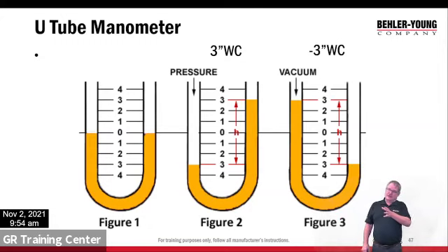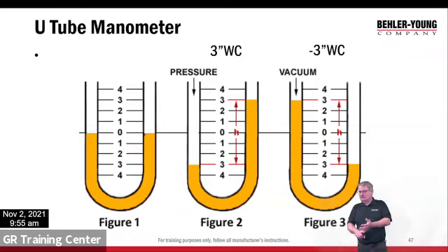On my return air ductwork, you may have never even thought about this, but there's actually a suction. We're sucking the air in. We can use this manometer to measure the static in the ductwork, to measure the static in your vent system for your pressure switches. So we're going to use this same little device to do it. This is a U-tube manometer, fairly inexpensive, but hopefully it makes some sense of what we're measuring here.